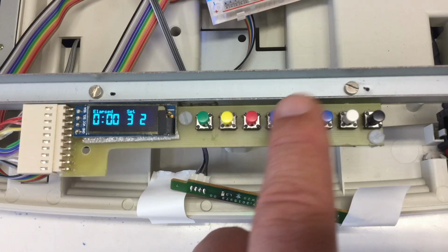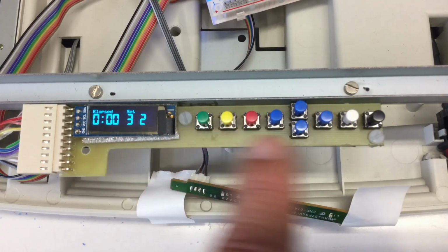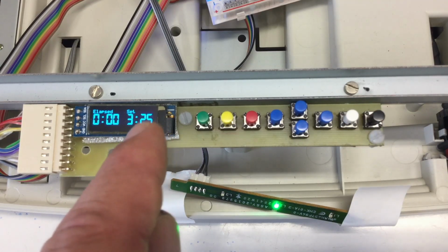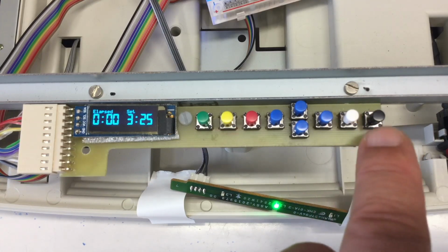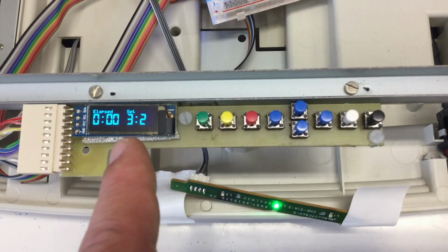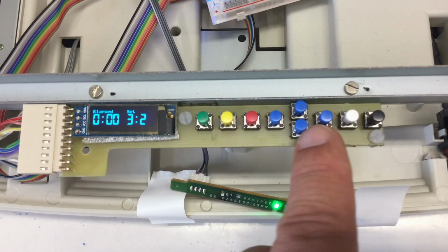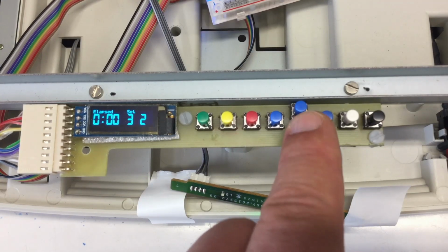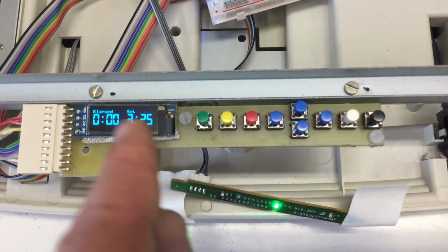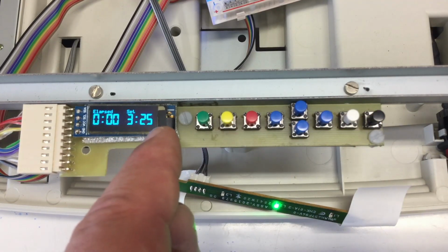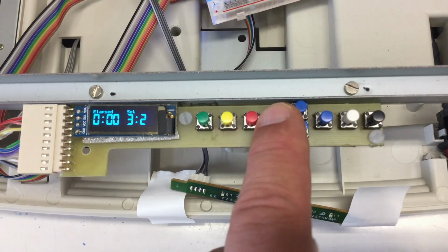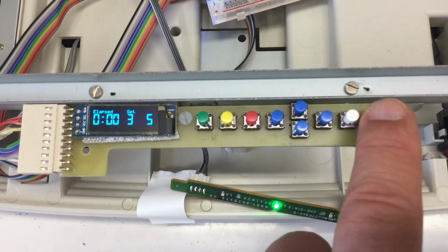And of course, as soon as my value is no longer the same as stored in the EEPROM, the colon will blink too. Just as a reminder, no problem, I can store this value with the black button, the store button, inside the EEPROM. Now the value is stored in the EEPROM. Change it and read it from the EEPROM. But the default value is read on startup from the EEPROM. Let me put that back to 3:15 and store that.